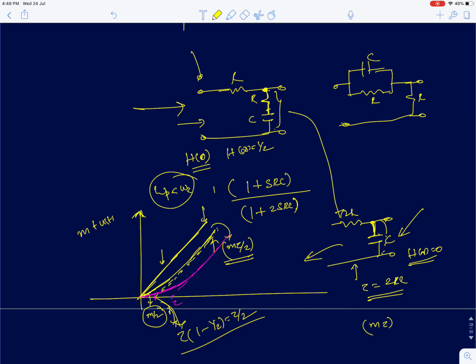Because it's rising quicker at t equal to 0, eventually at steady state the slope is the same as the input, so the steady state error also reduces. Compared to the pink curve, this one rises faster at t equal to 0. That's why it has a head start compared to the pink curve, and that difference is always maintained.